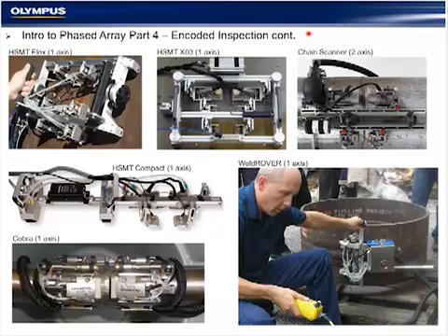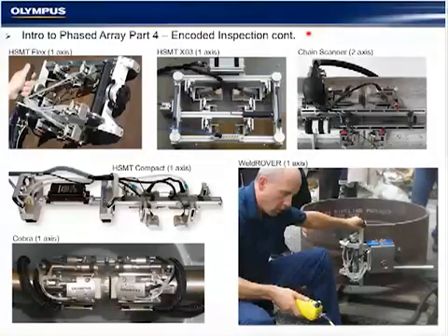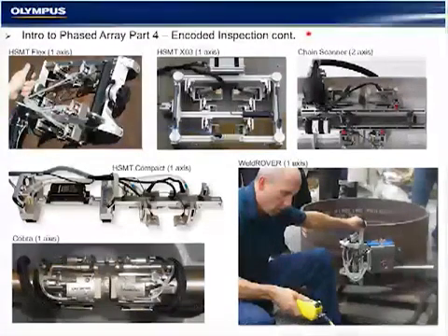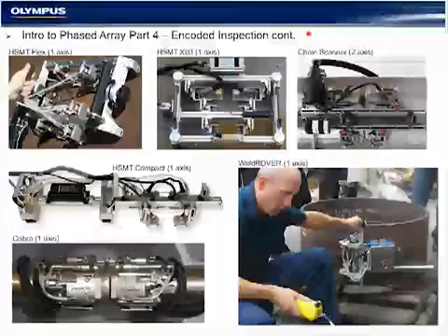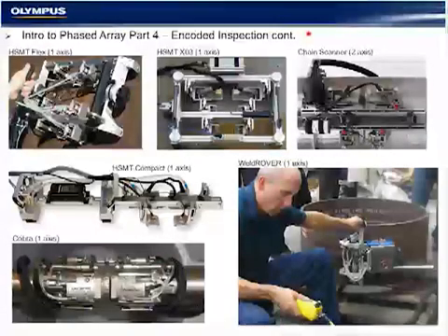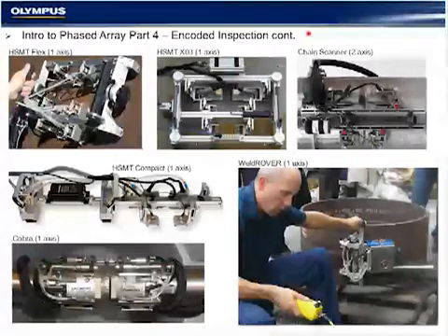What seems like an easy engineering task is actually very complicated. The best scanners are ones that are designed for one particular application. And the more a scanner is adapted to accommodate multiple configurations to include TOF, phased array, multi-probe, TOF and phased array in different one-sided, two-sided, access, automated, manual, the more versatile the scanner is, the more complicated it becomes. And again, the best of the scanners are designed and set up for a single axis or one component.